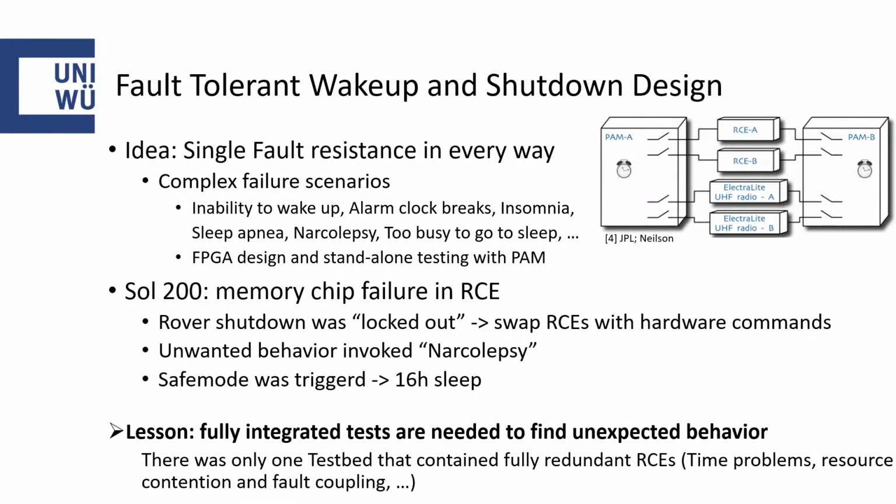So this system not only needs to be redundant in a normal way, but it needs to be single fault resistant. That means if one part fails in the entire system, it doesn't matter what. It's a cable that's broke or corroded, it's a switch that fails, it's a small FPGA that fails, it's a bit flip, latch up event, anything. The system has to recover itself without foreign intervention for any case, every scenario.